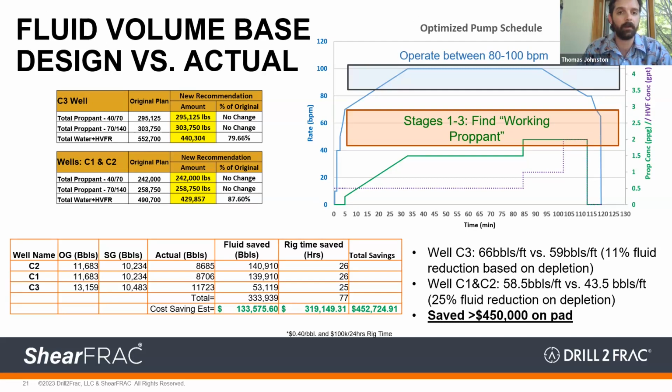So we've got very, very little pad and we're getting our proppant in as soon as possible. And then we're ramping that proppant concentration up to a higher concentration quicker than we would have traditionally done originally. So we're basically trying to ramp in. We know we're going to connect, but we're getting our proppant out there to divert our fluid away from that connecting fracture and back into our own wellbore.